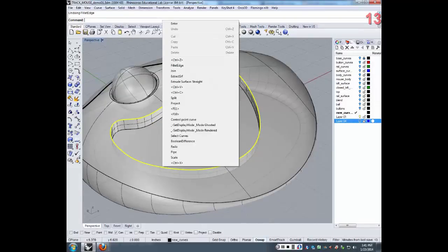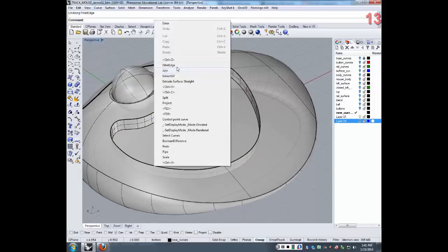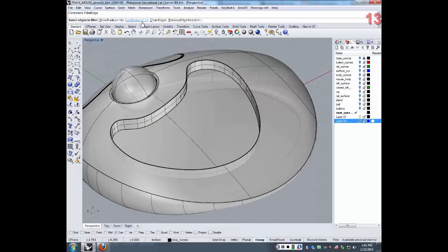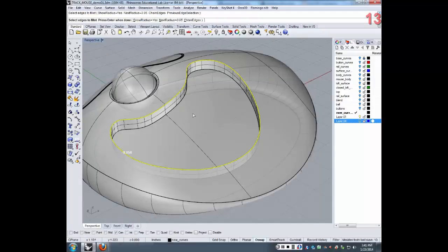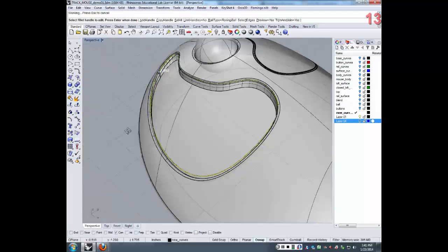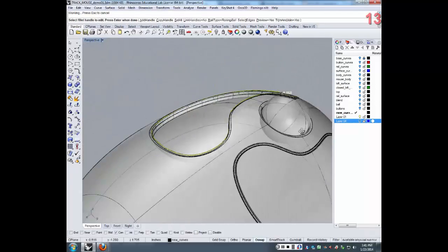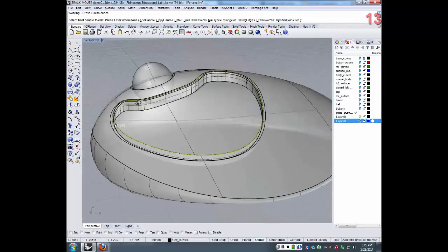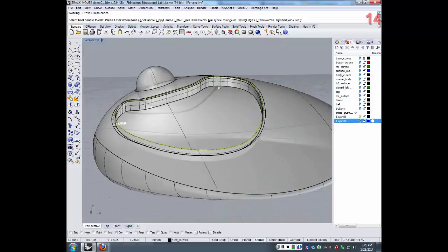And let me do a fillet edge. Well, we're at 0.08. I did that. Let's make this 0.05. And I'm going to select this edge to fillet. Now let me look over there. That's better, right? See, that's better? See how much better that is through there?